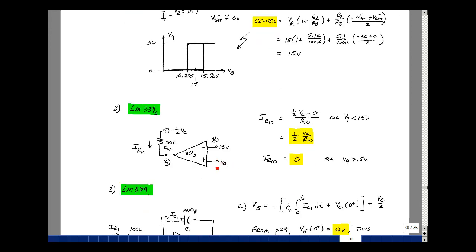Let's take a look at that third comparator. The plus terminal on this one is being fed by node voltage 9, which is our output from the hysteresis loop circuit. And then the other terminal was the voltage divider of a half. And so when the voltage across here is positive, then the output transistor is cut off, and there'll be no current flowing in here. When this voltage is negative, this becomes a short back to ground.